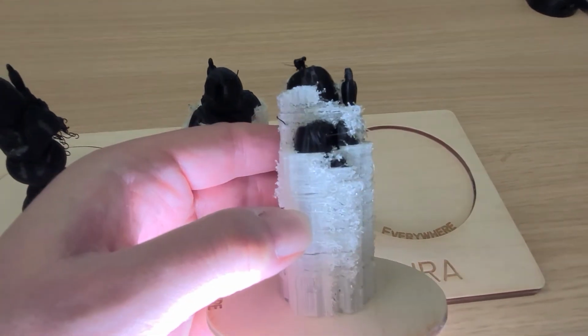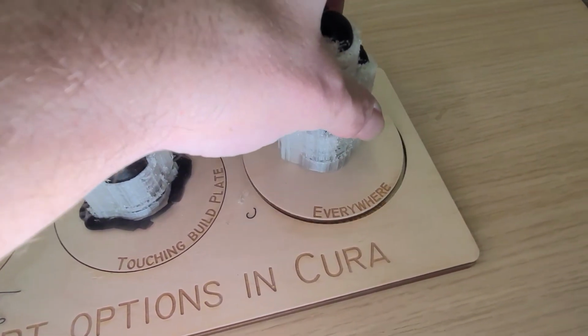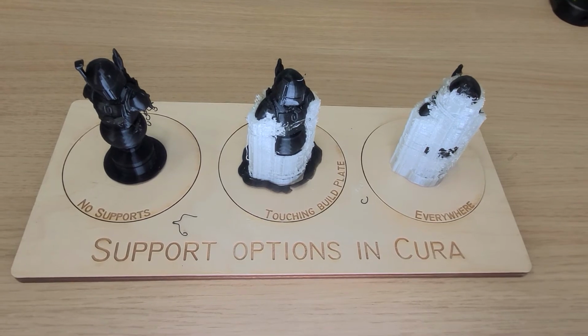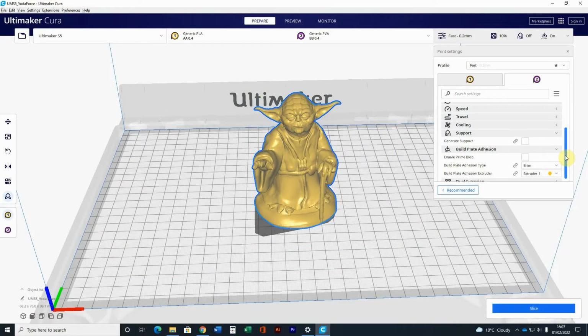Anywhere there is a bit of an overhang, it will produce support material. Now it depends from model to model which one you want to use. So sometimes if you want to make sure that everything prints as it should, you might want to use everywhere if you want to make sure nothing goes wrong. It can be a little bit overkill, but that's your options with supports.